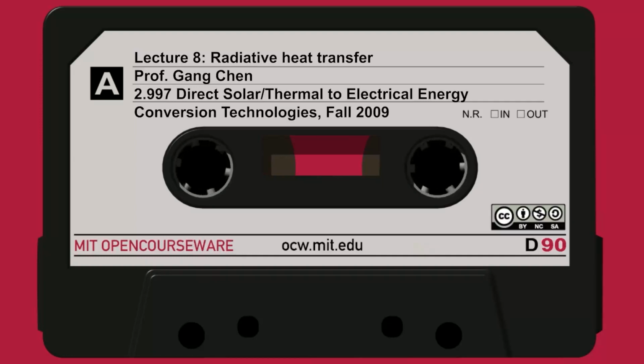So you have directional total, and then normally when you take an undergraduate course, you define emissivity. We typically talk about hemispherical total. That's the typical library. You look at a table for a heat transfer rate. So that's all directions, all wavelengths. Okay. So those are the definitions.